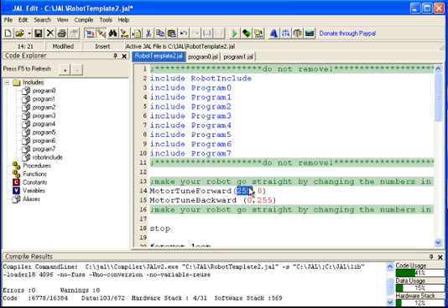That's the number we give it to go full blast forward. And 255, by the way, is the decimal form of an 8-bit digital binary number. And okay, so to go forward full blast on motor number 1, it's 255. To go full blast forward on motor number 2, it is 0. And that's what we've got our motors set at right now.